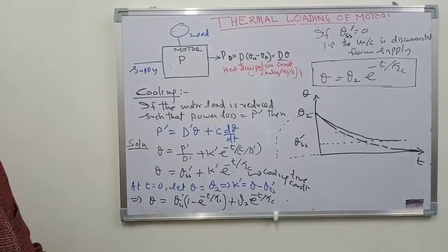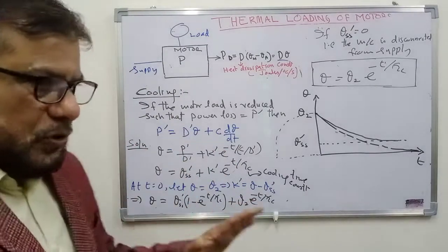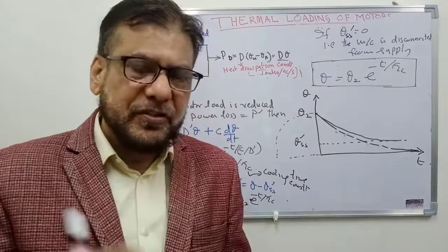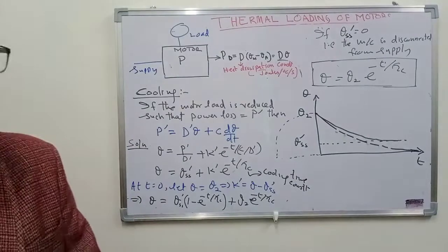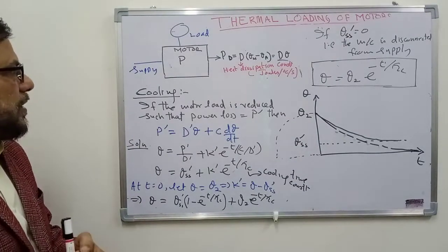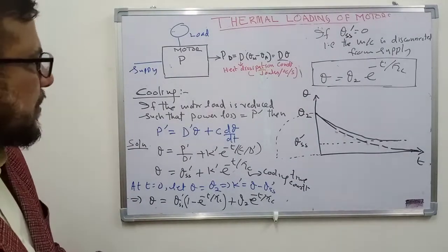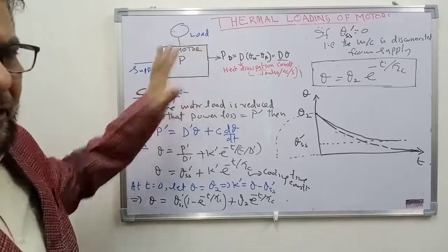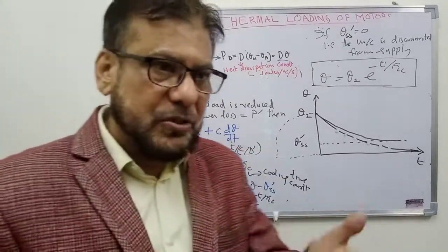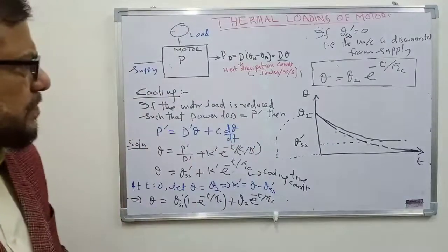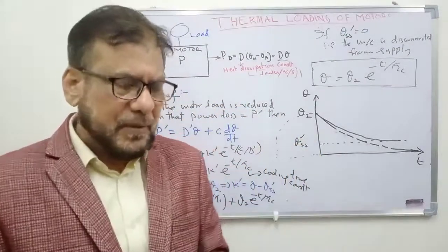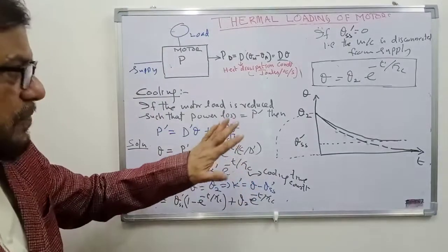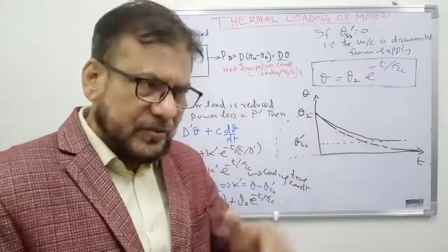So you have to know how to load the motor so that the motor reaches its designed value of steady state temperature rise. So we have to select the motor of proper rating. For example, if you have some certain situation where the load is coming only for short interval of time, the heating time constant is say 60 minutes.